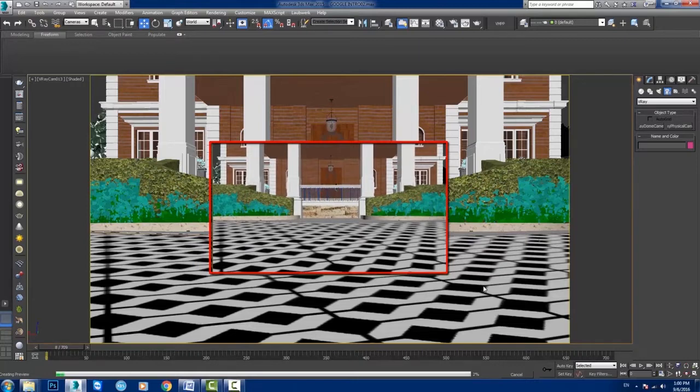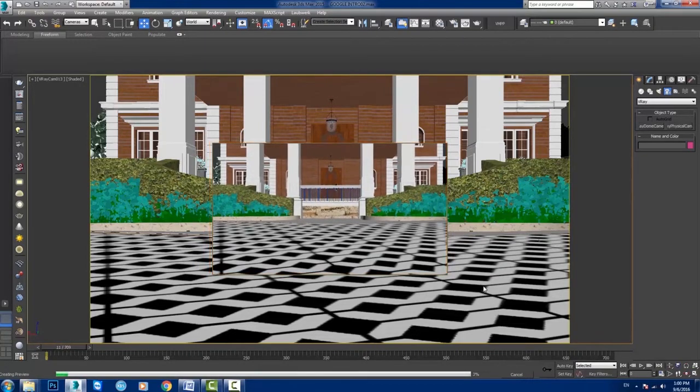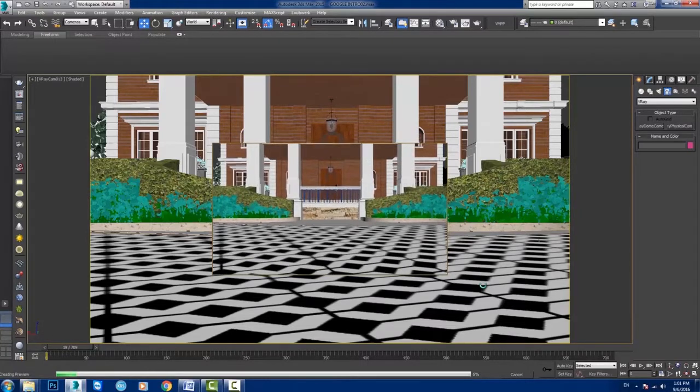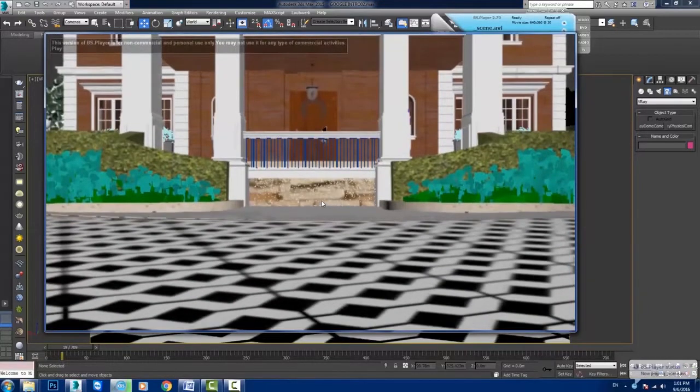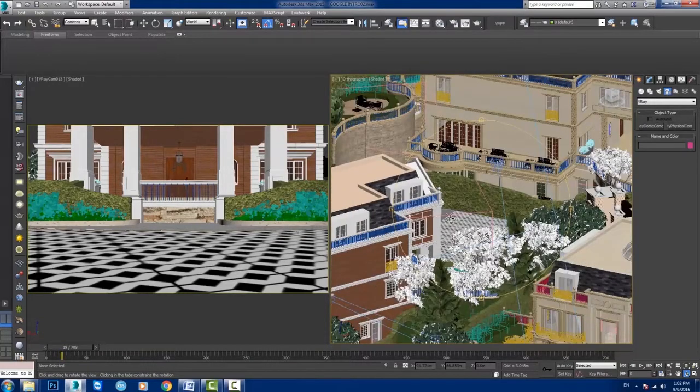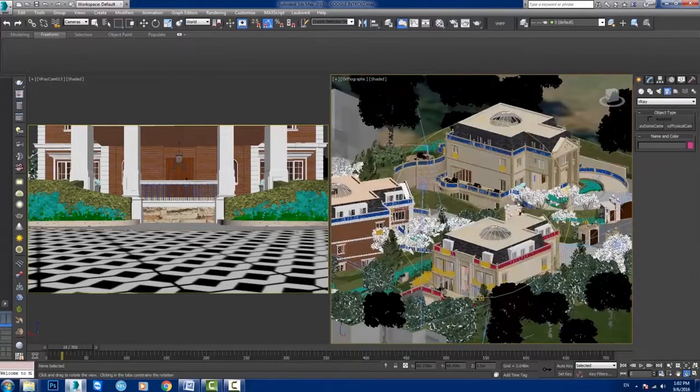middle of the screen. The speed of creation of that movie will be determined based on your graphic card and the poly count of your scene. If you find this process too slow, hit Escape. Max will ask you to play the part that is finished in the default media player. To make it render faster previews, we can hide the unnecessary elements in our scene.